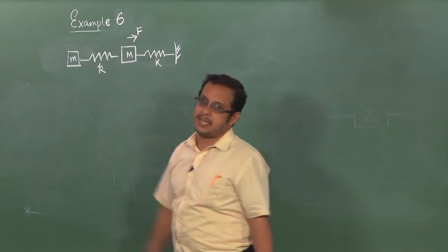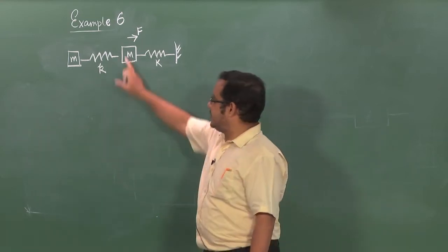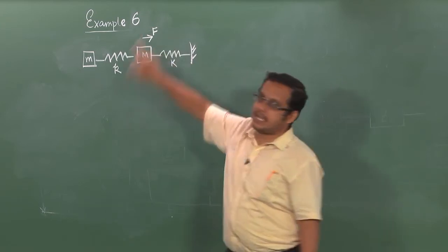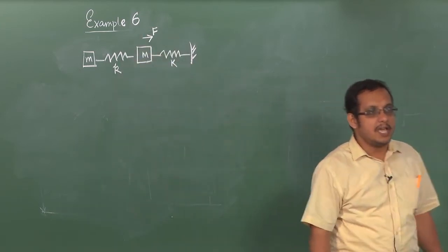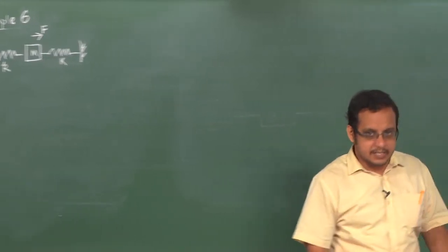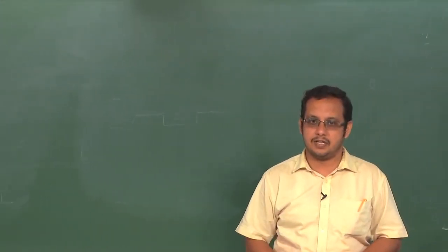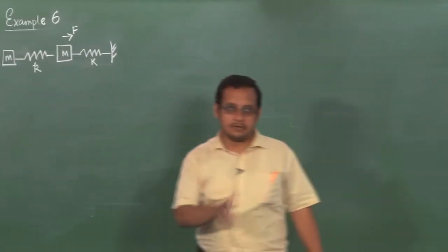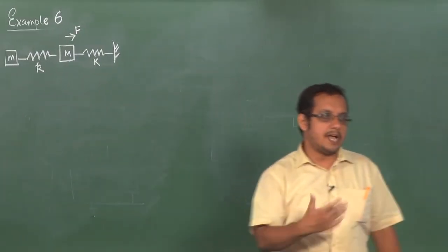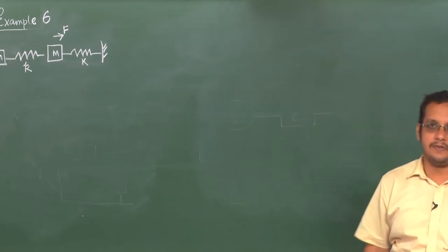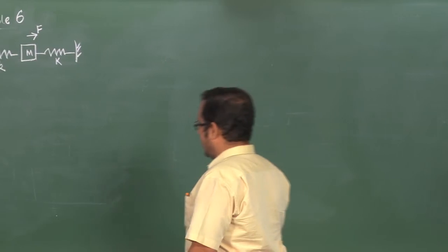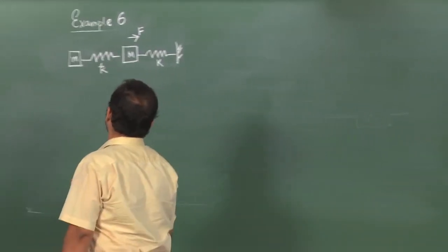another secondary spring and mass system such that the natural frequency of this spring mass system happens to coincide with the excitation frequency, and then if you work out the details from elementary vibration theory, you will find that the displacement of this primary mass is going to drastically come down. So, that is the usual derivation which will be given in a vibration course, but here we will appeal to the electromechanical analogy to explain this situation.